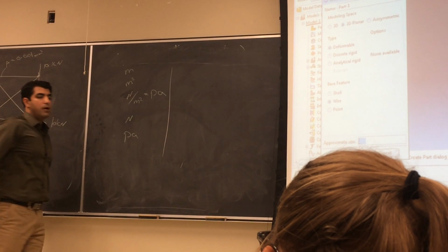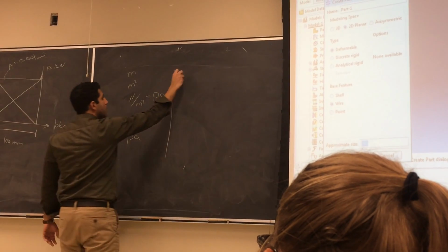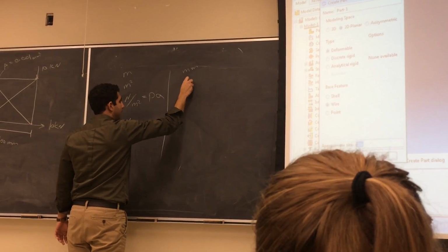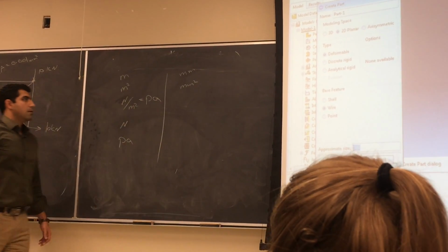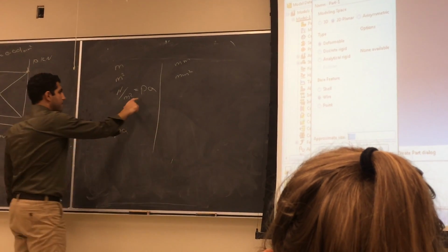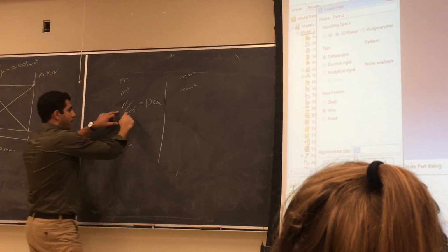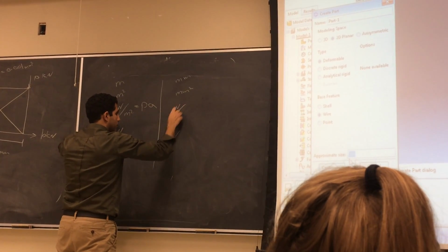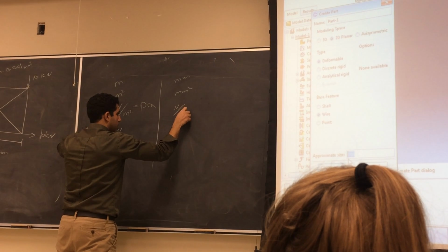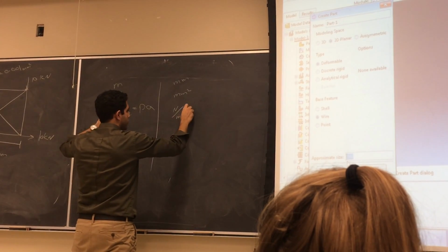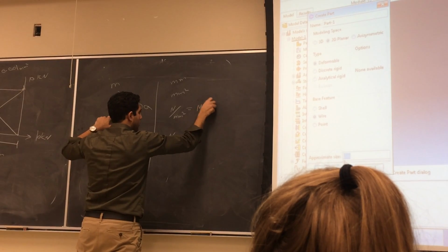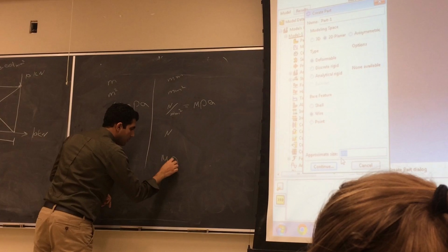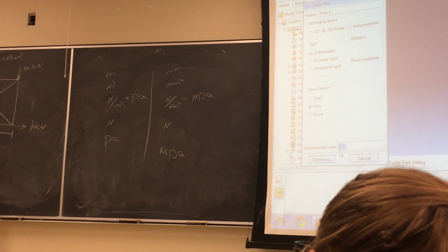In case you want to use millimeter, the cross-sectional area has to be millimeter square. Here for load you use Newton. For stress it is Newton over millimeter square or megapascal. The pressure is also megapascal.